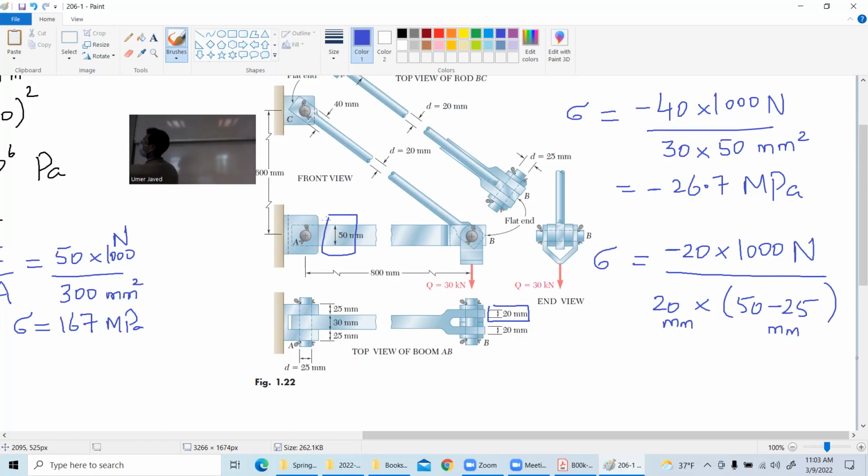The moment now I'm looking at the left leg, I see this hole. So now there is this chunk on top, and there is this chunk here. So I said 50 minus this hole, that is 25. Now I have to multiply with the width. For the width, I am multiplying with the 20. Do you get my point? So now I get a beautiful area right through which the force is flowing. Confusing? Oh, it's fine. This part I think for now we can skip. Just give me the value.